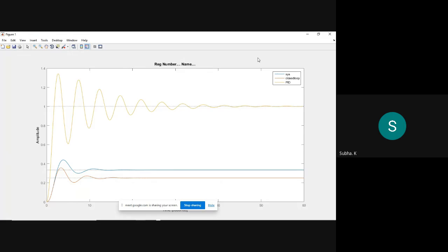If you want to reduce oscillation, you can by trial and error mix and match the values of KP, TI, TD, and you can try to reduce the overshoot. But here the settling time is not reaching at all, not available for all the other 2 cases. Here only the settling time is reaching.